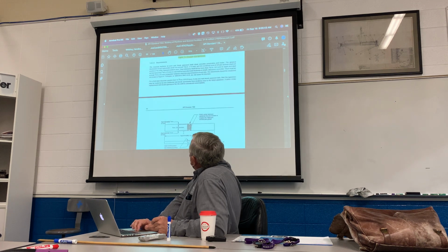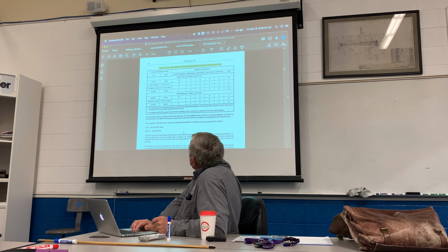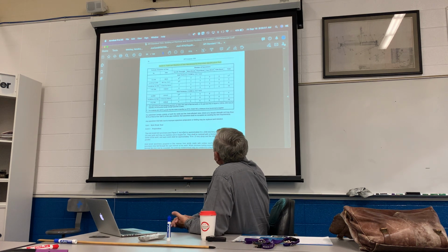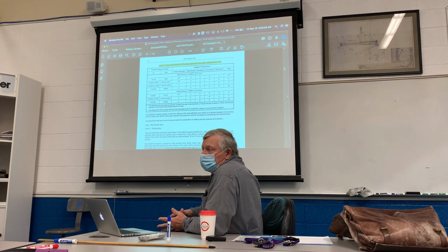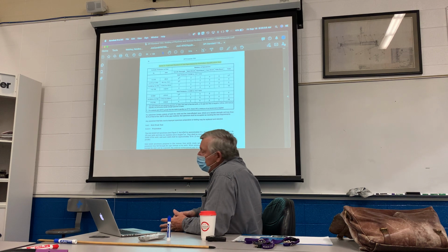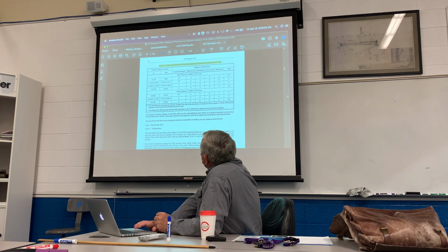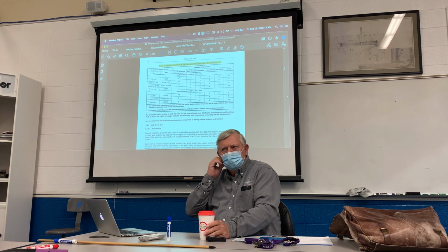Okay, just zipping right along here then, we're gonna look at a couple more things. Here is the table, this is table 2. This is the table and number of test specimens for the procedure qualification test. So if you're doing a test where you're qualifying a procedure, this is the chart that you use. So most people use this right here, 12-inch pipe. Why would you use 12-inch pipe? Because it qualifies you for everything that you need.